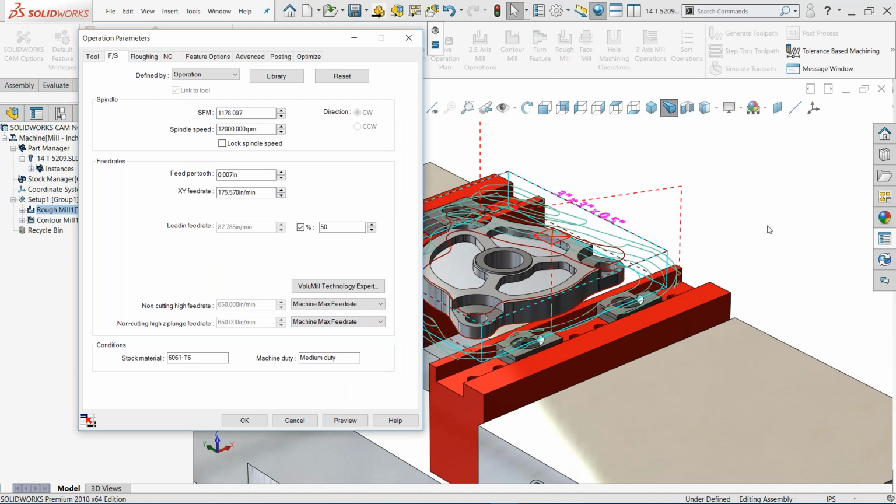So high-speed machining really allows us to take kind of arc-like motion rather than hard left and right motion, so it's easier on the machine. It does a constant volume loading, and it does the full length of the flute typically. And so what this does is it speeds up the entire process and also saves the life of our tools.